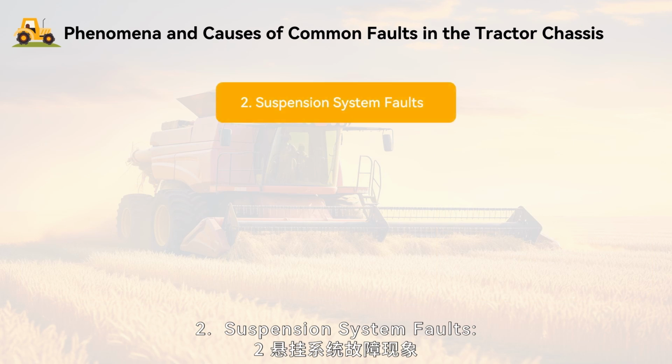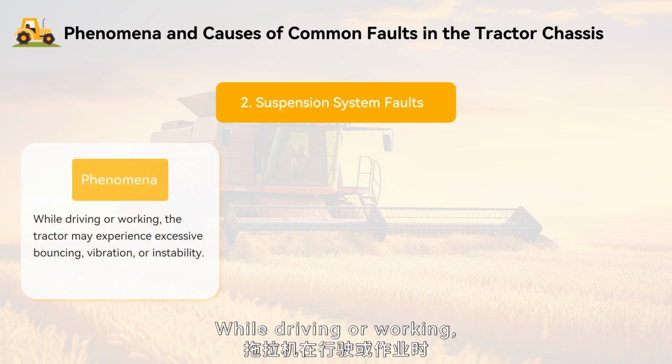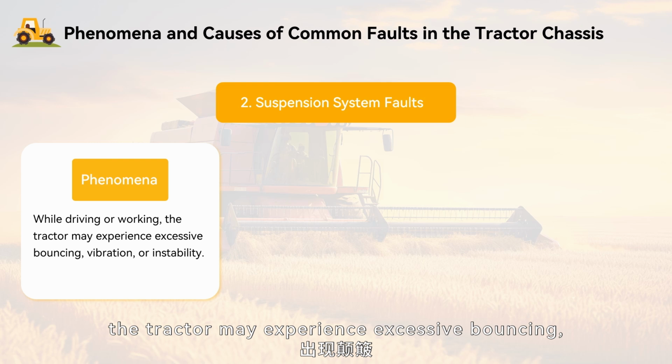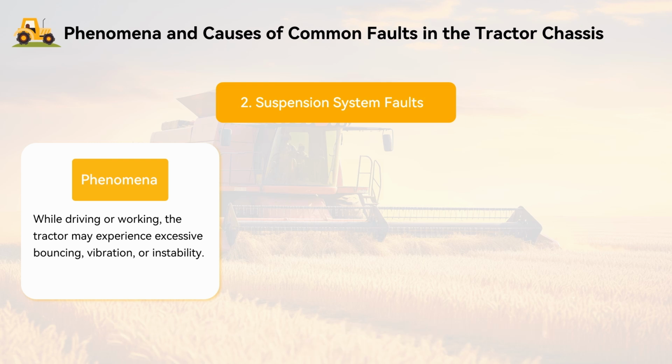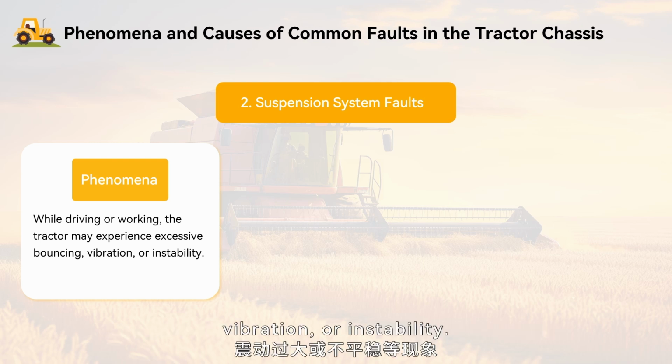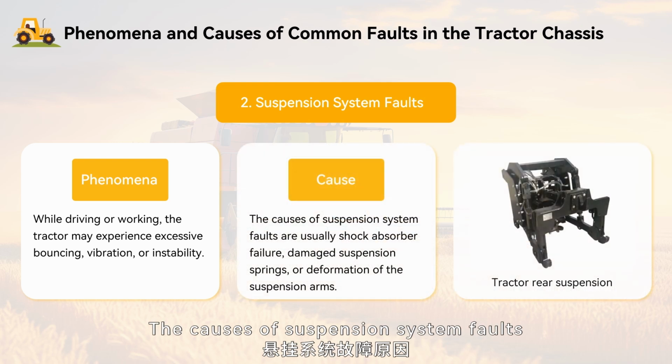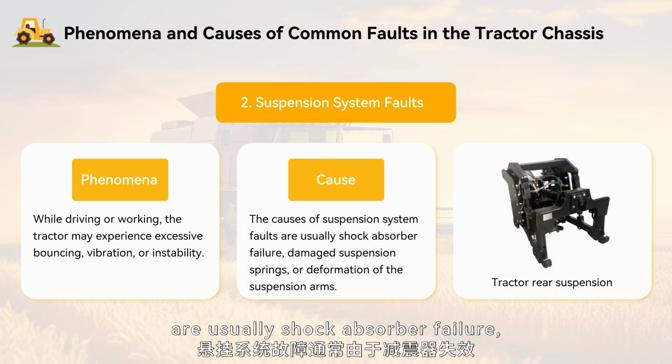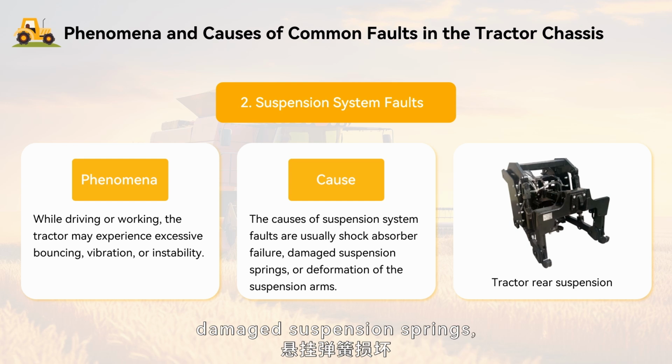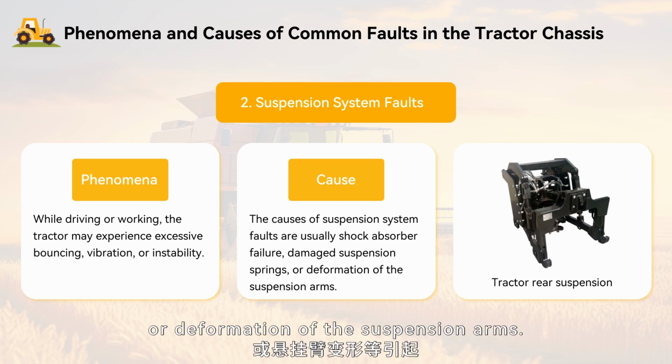2. Suspension system faults. While driving or working, the tractor may experience excessive bouncing, vibration, or instability. The causes of suspension system faults are usually shock absorber failure, damaged suspension springs, or deformation of the suspension arms.